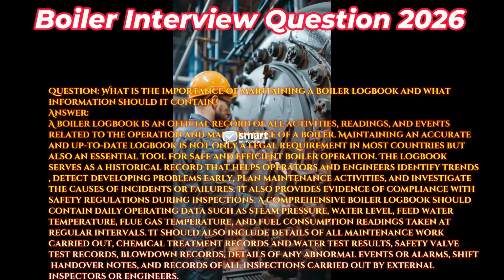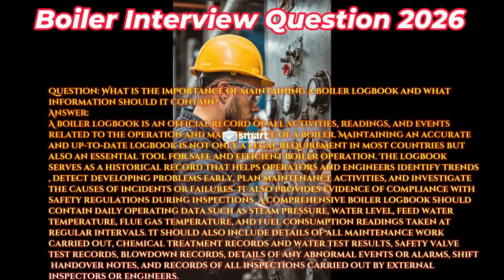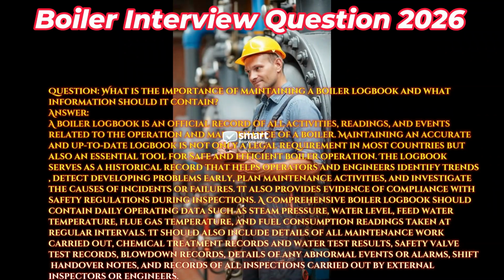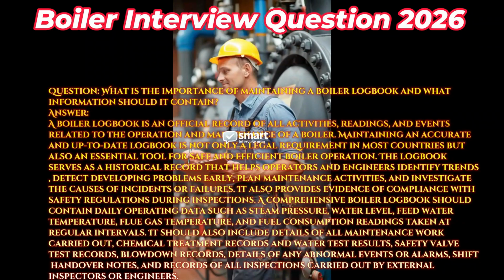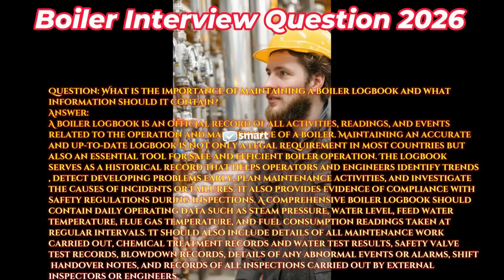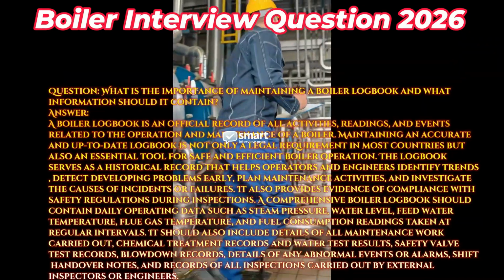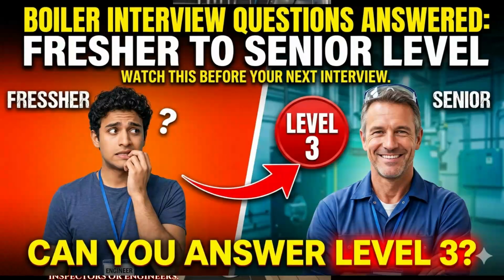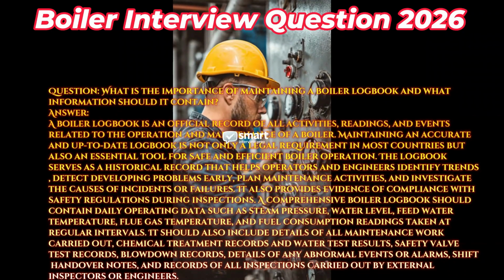The logbook serves as a historical record that helps operators and engineers identify trends, detect developing problems early, plan maintenance activities, and investigate the causes of incidents or failures. It also provides evidence of compliance with safety regulations during inspections. A comprehensive boiler logbook should contain daily operating data such as steam pressure, water level, feed water temperature, flue gas temperature, and fuel consumption readings taken at regular intervals.